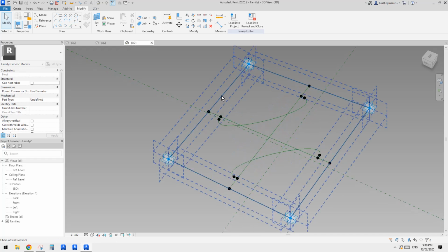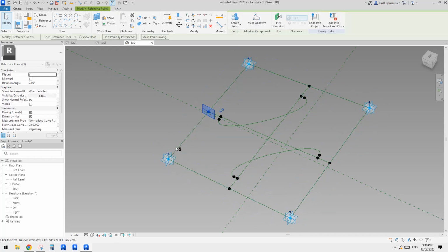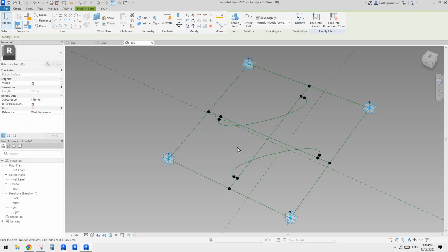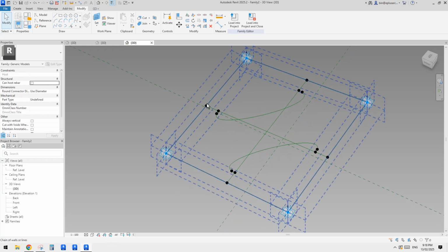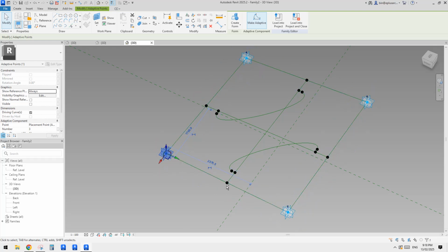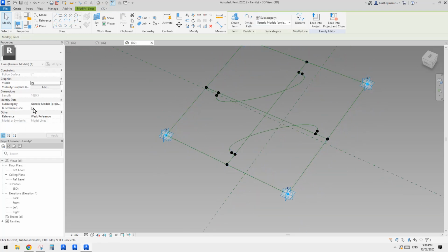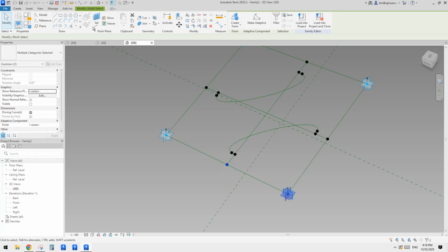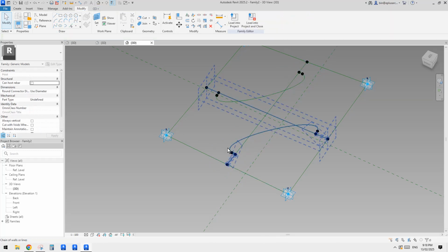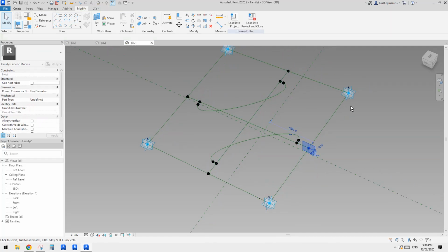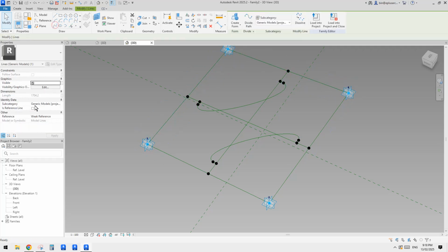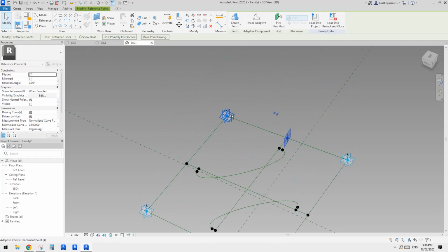Okay. So we don't have this. So yeah, we also need this as well. So let's create all these reference lines. So previously we only have one from here to here, but looks like we need all the individual half reference lines, because we need all these closed loops, right? So let's continue all these reference lines. This one and this one, spline through points, reference line, this and this.